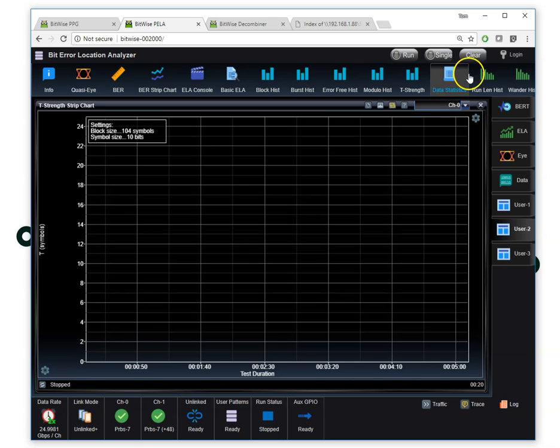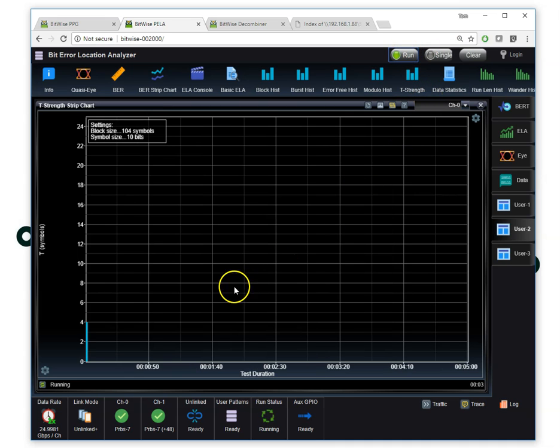Then I can run my data through here, and the analyzer will show me over every interval of time what correction strength I would have needed to get error-free performance in that interval. Now, unfortunately, the error that I'm causing right now is a little simple.